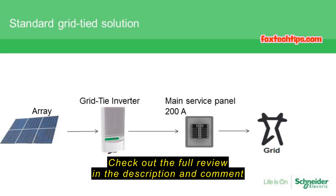So a very standard grid tie inverter. Here we have a Schneider product as an example. The array comes in through that inverter and steps it from DC into AC, and then on out to the main panel and then onto the grid. Though there may be a supply side tap here instead, going around the main service panel. Typically we'd see a meter between the grid tie inverter and the service panel, and of course the home would still maintain its grid meter.